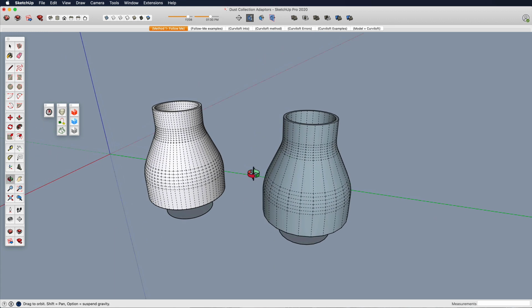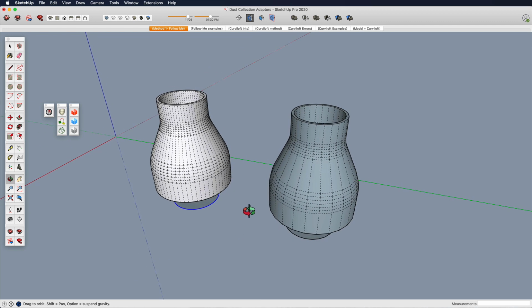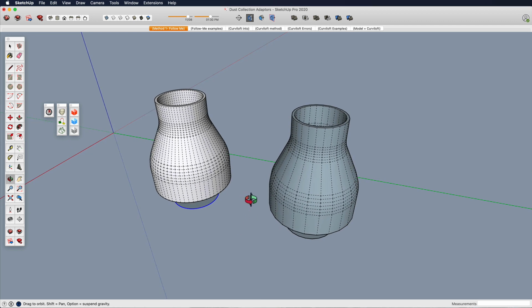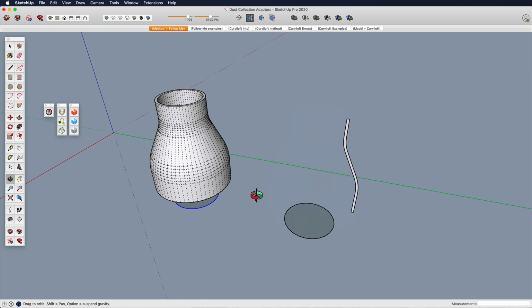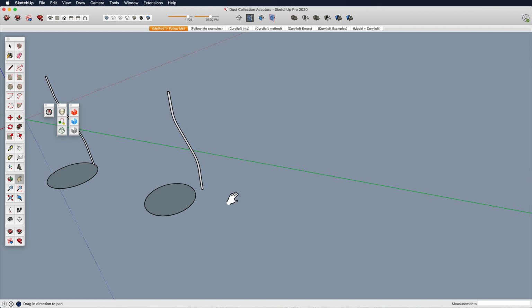If we look at the segments that are created, again, this was 24 sides and this was 60, and you can see there's more, and your surface is going to be a little bit smoother. You don't need to go up much past that. You can go higher if you want, but you don't really need to go above 60 or maybe 80. So with that as one intro, let's build out an example.